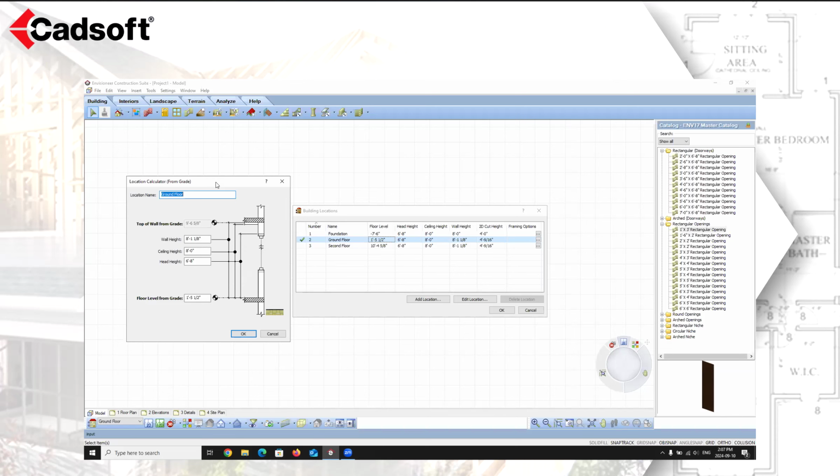That's going to include whatever the thickness of my floor is, plus whatever I have exposed of a foundation wall. If you take a look at our foundation, we can see that the wall height is 8 feet, but only 7 foot 6 inches of it is below 0. That means 6 inches is exposed. So this 1 foot 5.5 inches includes 6 inches of foundation wall, plus the thickness of my floor and my sill, as well as the thickness of my floor sheathing. That is where that 1 foot 5.5 inches is coming from.